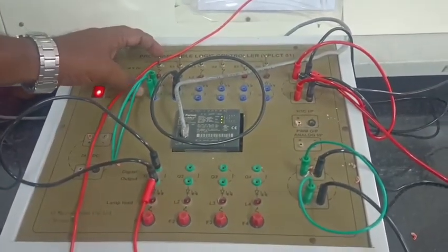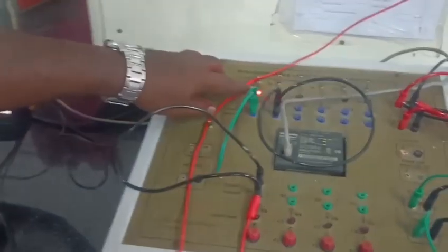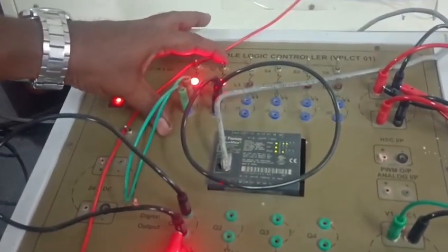If we are using an AND gate operation and you put the switches, here the I1 switch is on and simultaneously it will be energized, but the output is not obtained, because for an AND gate, only if you give two inputs can you get the output. So you need to energize another input. You have to press another switch, then the other input is energized and you can get the output.